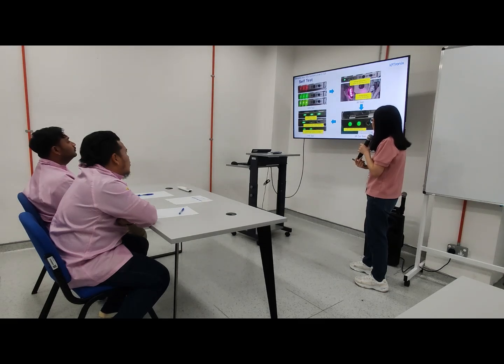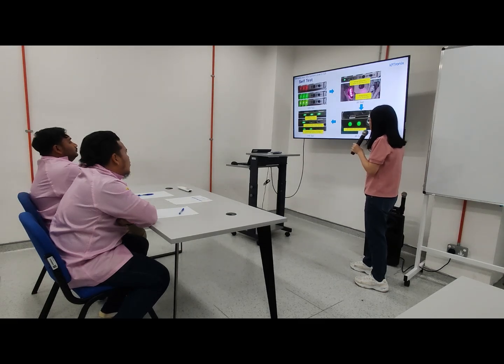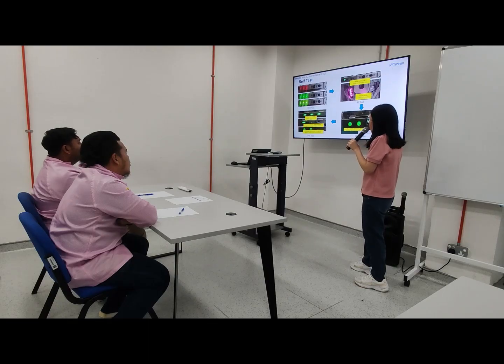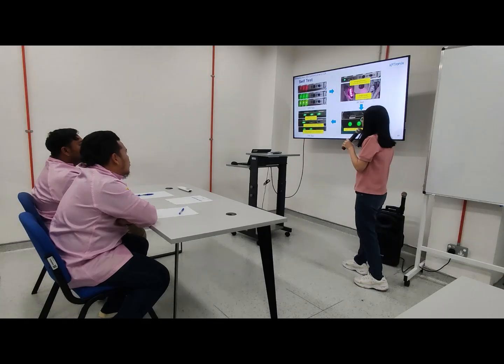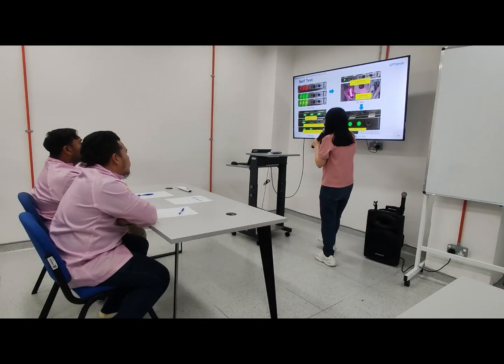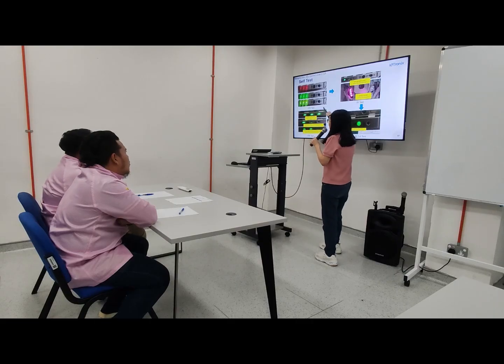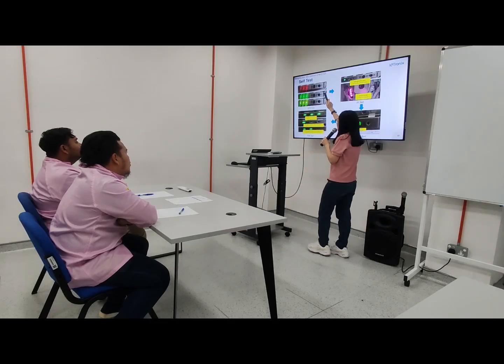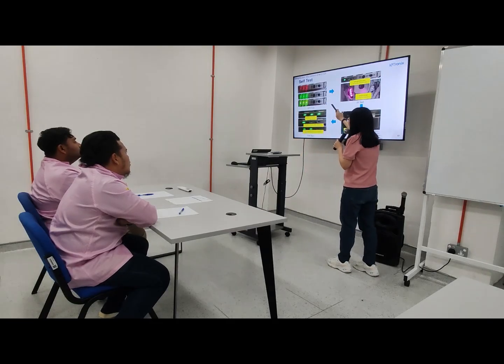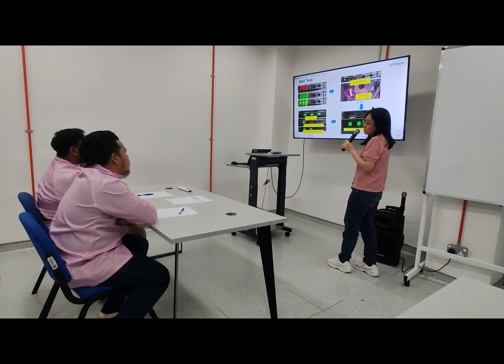Next is about the self-test. Self-test, actually this one for the 4G model, the test steps are the same. First, we'll go for the LED test. This one is first, when we open up, it will show 3 red lights, 3 green lights, and 3 yellow lights. This one is for the LED test. After the LED test is complete, we will go for the next step.